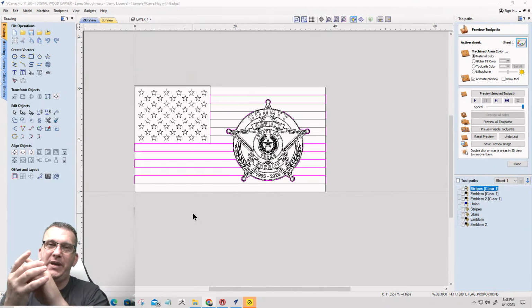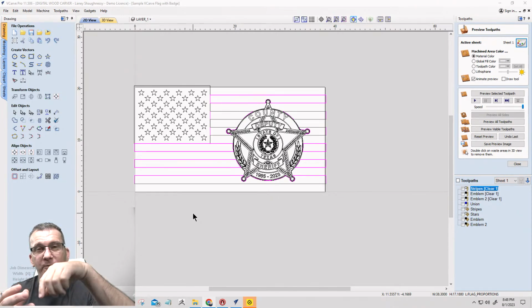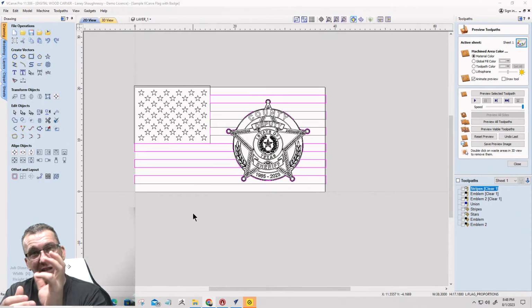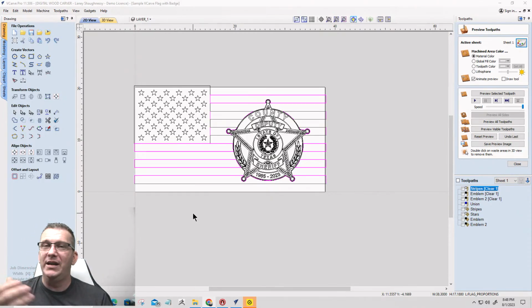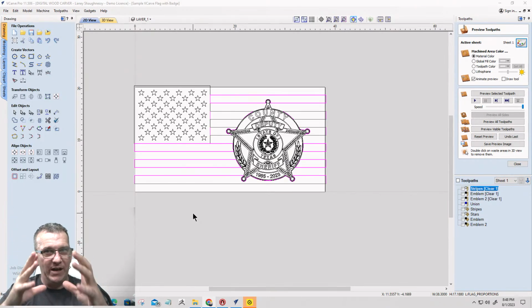Reverse that. Also, the smaller the bit, you need to start slowing things down as well. Because as your bit gets smaller, the gullets and flutes on those cutters get smaller, they can't produce too much of a chip. If they're spinning too fast, they can't really cut, right? So that bit needs to slow down. I've run 1/8-inch end mills at 12,000 RPMs at times. I'm not saying that's good, but you can fine tune your cuts and see where you need to be.